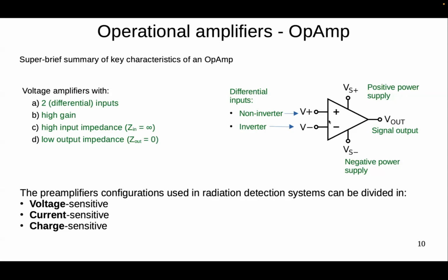The minimal change on the difference of these inputs will create some very high amplification that very easily can reach the maximum, so this is voltage Vs from the positive supply, or the minimum. So it kind of saturates very easily with a very small change from the voltage difference on the inputs.